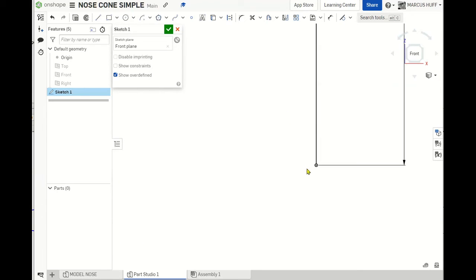And now we're going to add 2 boxes here to define the part that goes into the rocket and then a place to connect our nose cone to make the cone at the top. So I'm going to choose a 2-point rectangle, make it a construction line, and click at the origin, drag it out, and click somewhere for this dimension.